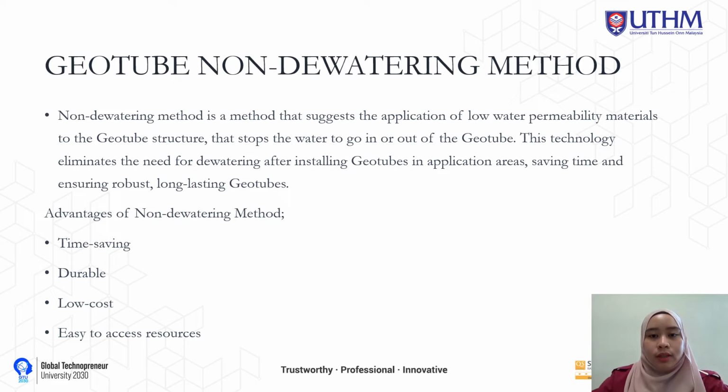To accommodate the non-dewatering concept, a low permeability material is required to prevent water from entering through the geotubes. As a result, the non-dewatering method geotube is used in conjunction with a plastic film, which is linear-low density polyethylene.